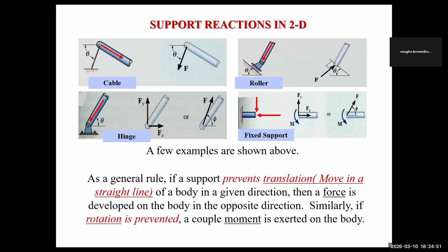It will show you that there's one single force coming off it when it is pinned there in that cable. What about a pin? When you have a pin joint, you always have two forces, and the other figure shows you over here the resultant force of the two. The fact that you have X and Y means that you have a resultant for both of them. And it shows you, phi shows the angle of the resultant force.